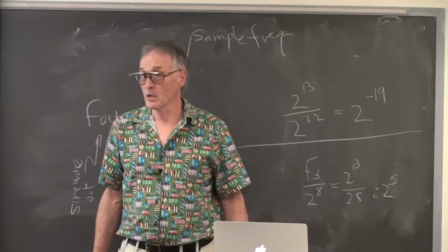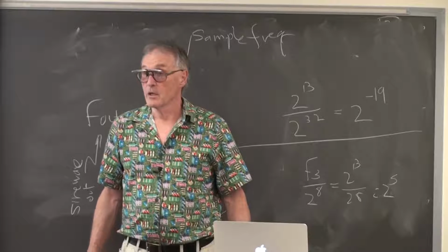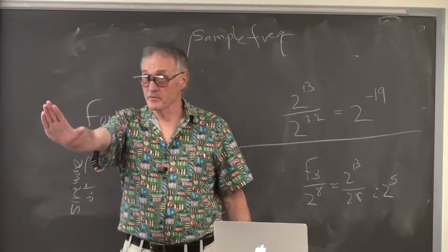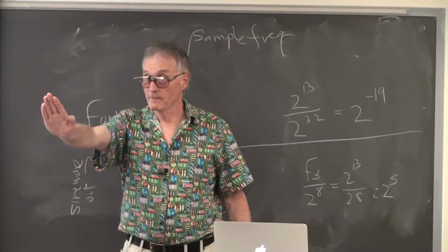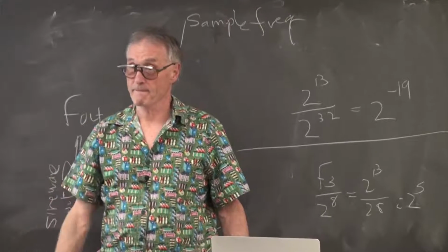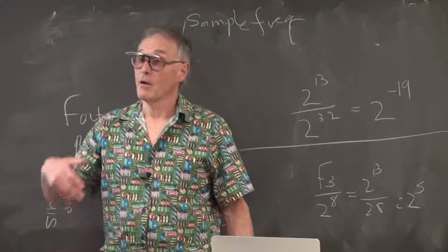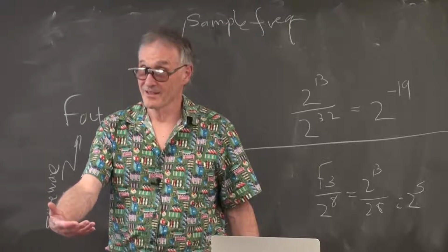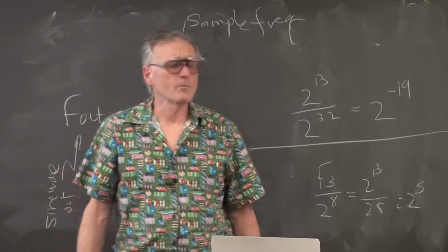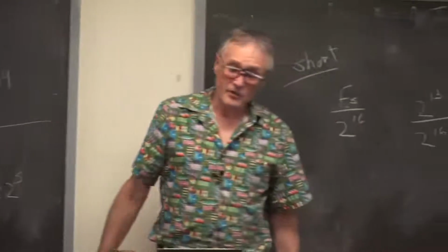Does it work? At what frequency synthesis? Like basically all the DTMF. What frequency of interrupt service routine? The clock is 40 megahertz and the service frequency is like 5,000. What's the frequency? 8 kilohertz. Right? So maybe on this architecture, a floating point will work.